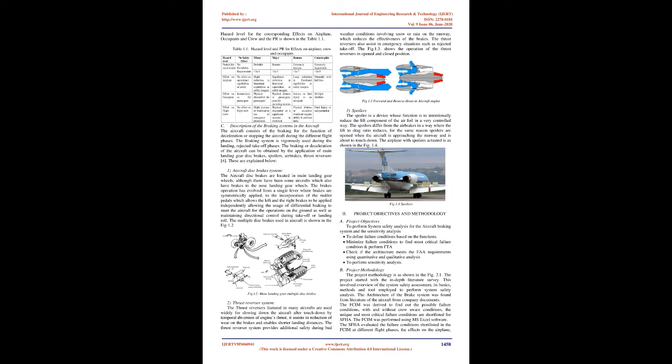The brakes operation has evolved from a single lever where brakes are symmetrically applied, to the incorporation of the rudder pedals, which allows the left and the right brakes to be applied independently, allowing the usage of differential braking to steer the aircraft for the operations on the ground as well as maintaining directional control during takeoff or landing roll. The multiple disc brakes used in aircraft is shown in the Fig 1.2.